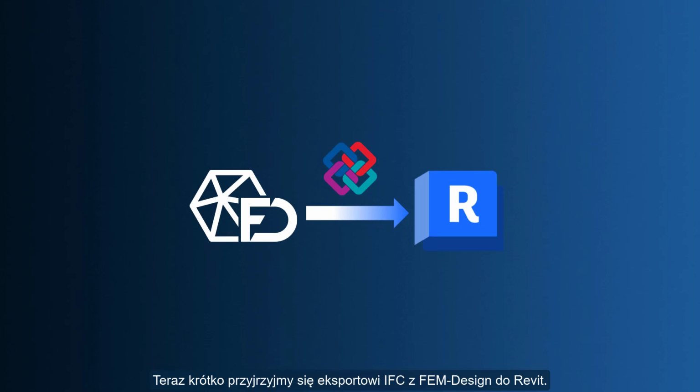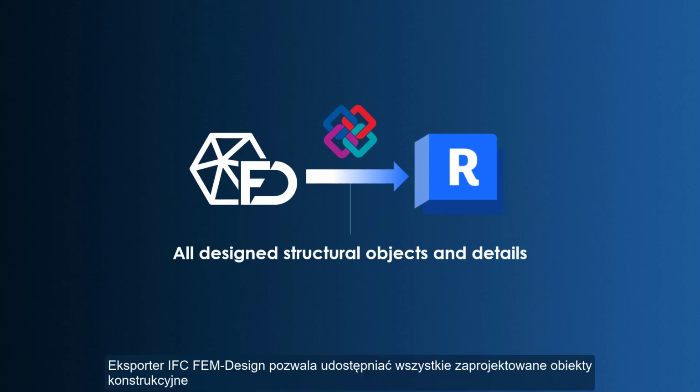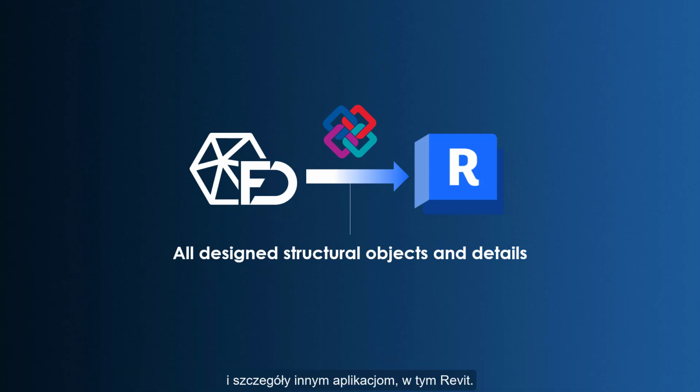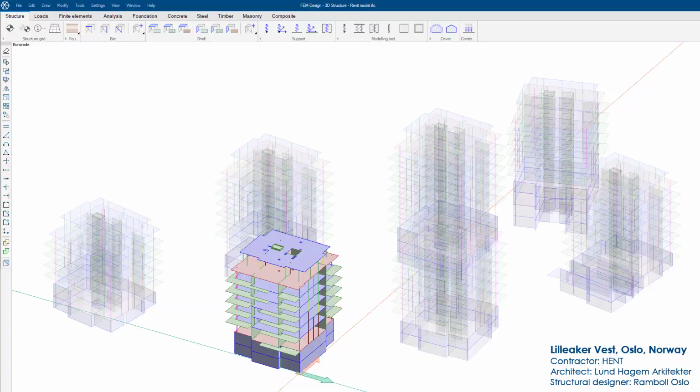Now let's briefly look at IFC export from FEM-Design to Revit. The FEM-Design's IFC exporter allows us to share all designed structural objects and details with other applications, including Revit. If a FEM-Design project contains several models, we can export only one selected model. We can also define a user coordinate system and export relative to that system.